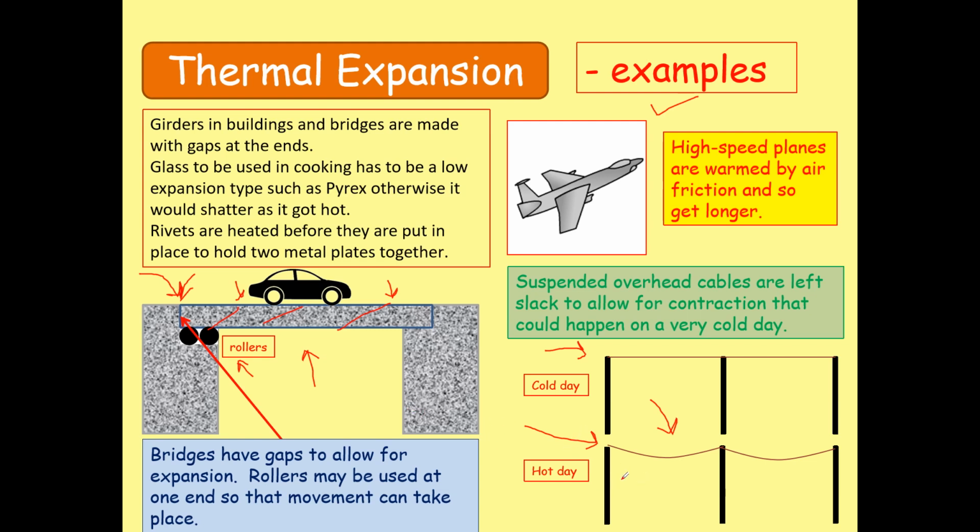So you need to understand that during summers they tend to bow a little bit. Why? Because aluminum is expanding, and these pylons have a fixed gap between them. Then the aluminum definitely needs to bow a little bit to account for the expansion during summers, right? I hope this covers a little bit of thermal expansion, right?